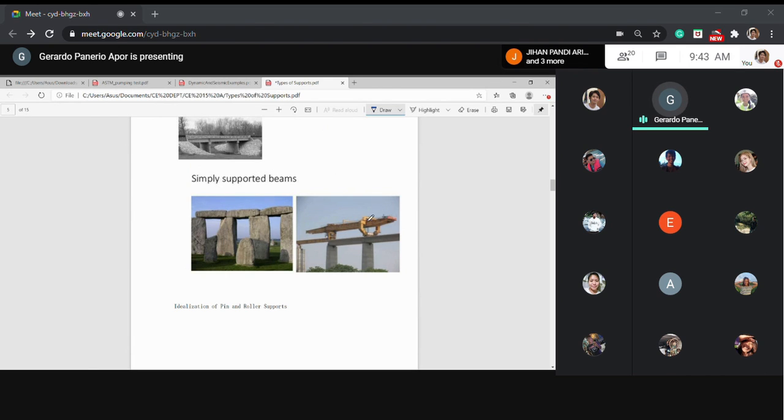Actually, this is a bridge. And you can see the equipment at the top. This is a modern girder launcher. No? So it could launch girders in just a few hours. It picks up a girder, then moves to the other point, then places it. So that is its job, placing girders. These girders are prefabricated far away in a factory, no? Sometimes these are factory manufactured.